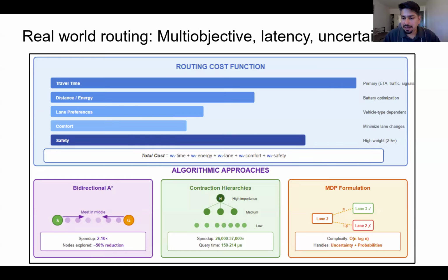If you model it as an MDP, a Markov decision process, where there is a probability assigned to each action, solving an MDP of this nature is typically O(n squared) in time complexity, and this will not work on a vehicle. It will be quadratic or even exponential in nature, and you will have a really slow search. And we want results as soon as possible.